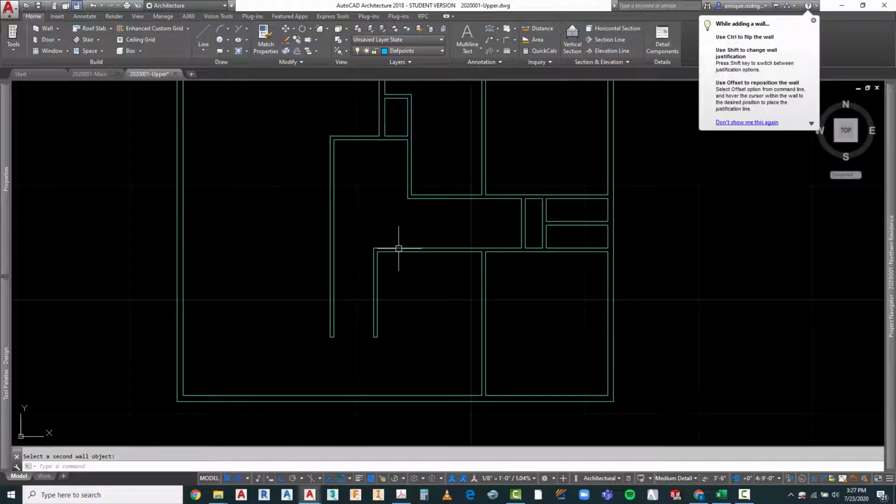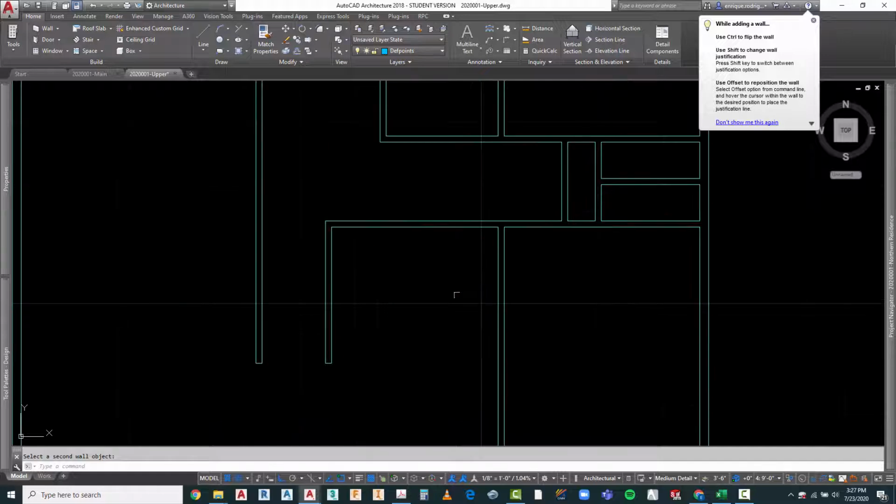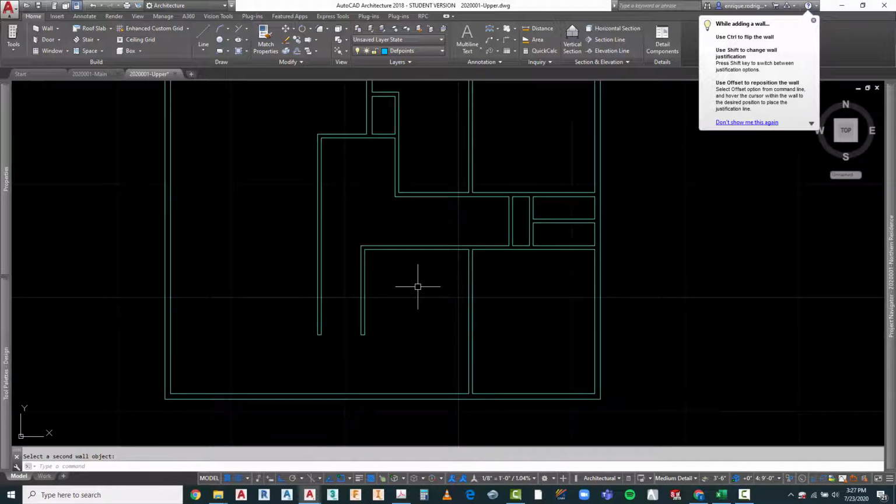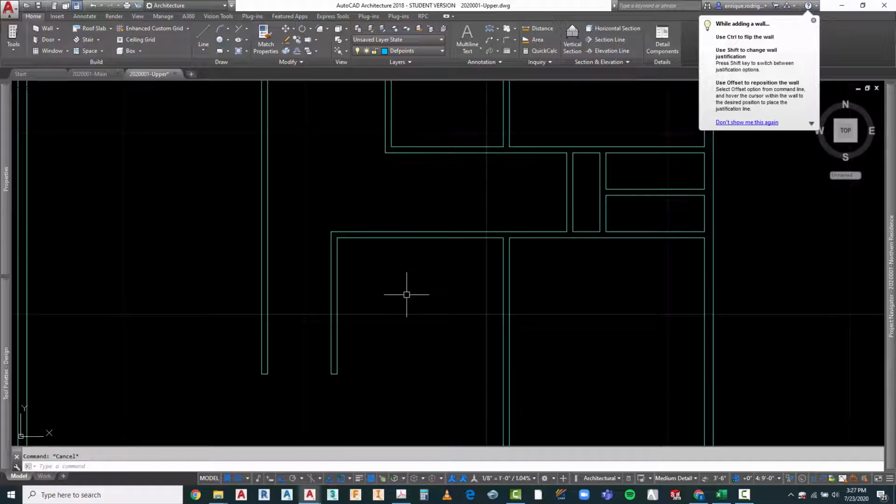And now what I want to do is put the toilet compartment here. I'm going to go ahead and put the space that's going to be leaving for the shower. I may want a little bit bigger shower than I've got available in there. So first thing I'm going to do is, they say 6'2" and 1/2 inches for the enclosure. I'm going to go ahead and copy this. And I'm going to copy it 6'4". Okay, and see what that leaves in terms of the width of my shower.